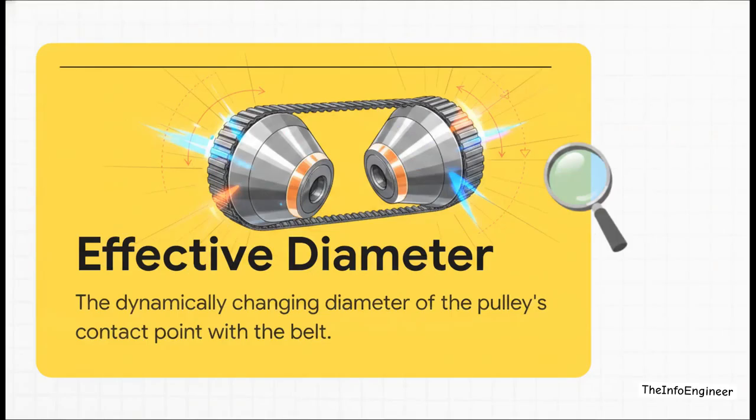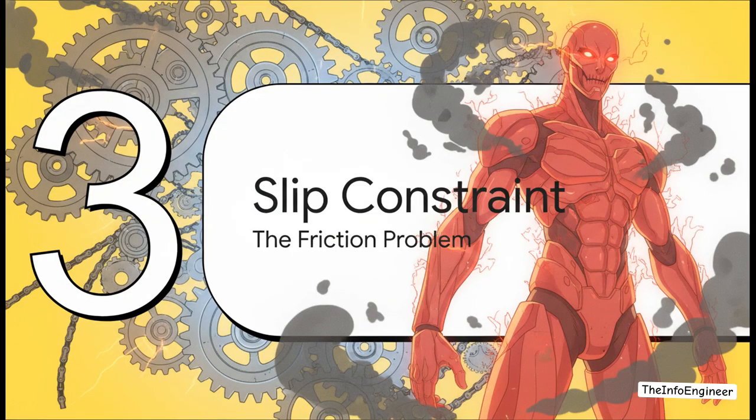And that brings us to the concept of effective diameter. This is the dynamically changing diameter of the pulley's contact point with the belt. As the belt rides higher or lower on those cones, the effective diameter changes instantly, and that's exactly what determines your output speed ratio. Here's where the engineering gets incredibly precise. Both the belt and the inner walls of the pulleys share an exact 22-degree cone angle. Because they match perfectly, the belt has full, flush contact no matter where it sits on the radius. And that is what allows the system to create an infinite number of ratios, perfectly mapping the engine's output to the wheel speed.